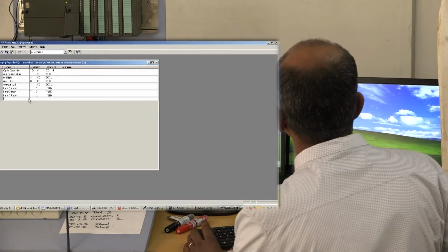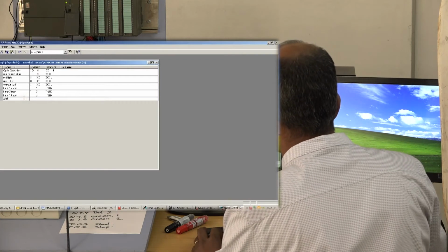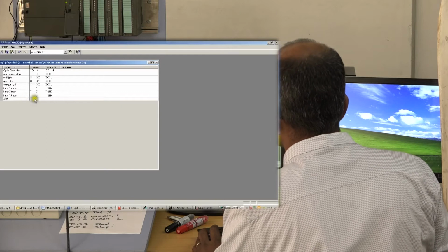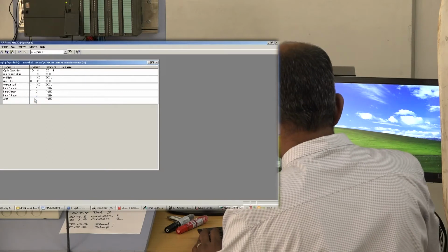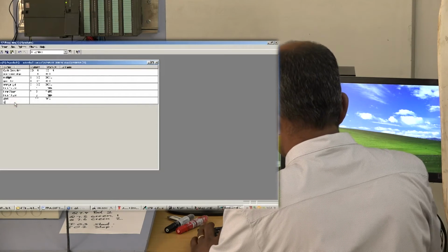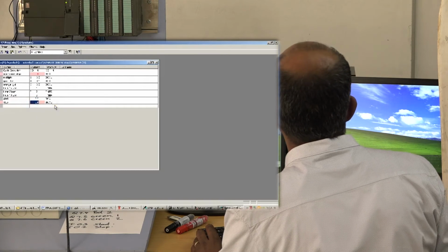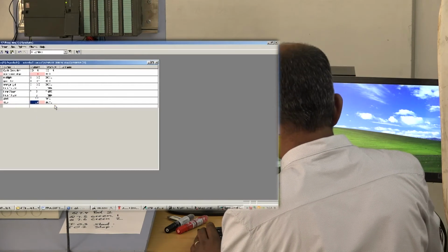I just need to add my start and stop. So I'm going to say start, S-T-A-R-T, is I0.3. Stop is I0.2.